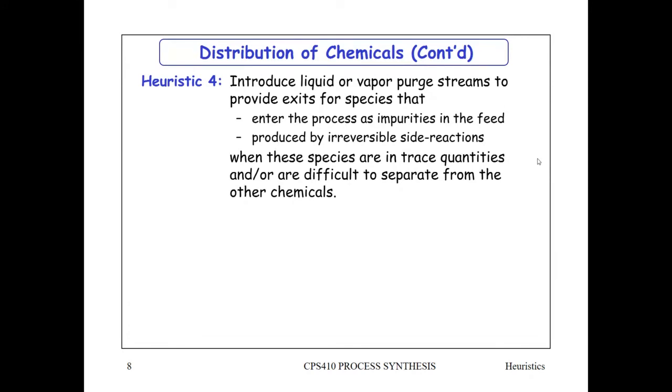We had argon entering with the synthesis gas, the hydrogen and the CO. Where can that possibly exit that process if ammonia comes out as a liquid in the gas liquid separators? The only way to remove that argon is to put in a vapor purge stream.